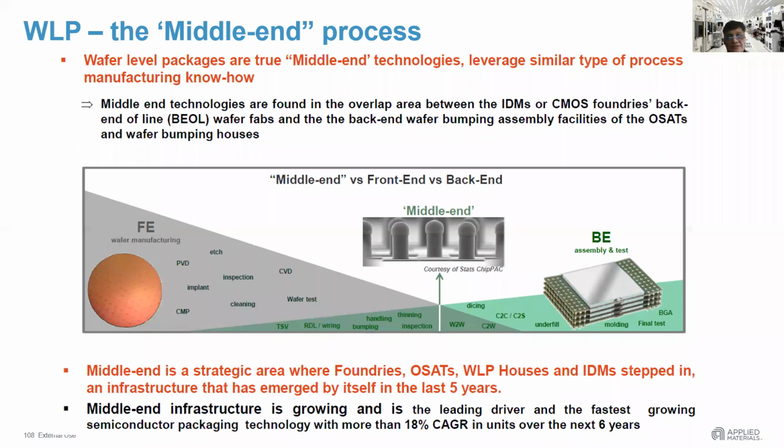And this involves doing all the oxidation, creating the dielectric layers, depositing different types of materials, planarizing them, passivating them, then selectively patterning on it, etching on it, selectively creating those shallow trench isolations, creating those vias, creating the transistors by appropriate doping, and then building the interconnect.